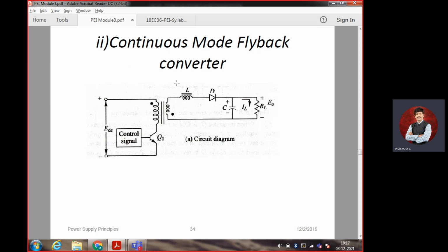So the major advantage here is the inductor. This will store the energy, and this energy will keep on being sent to the load. IL keeps on coming. Previously we depended on the capacitor, but now that we have included the inductor, it will take care of continuous operation. Whatever energy was there is going to continue. Since it is continuing, the separate modes will not be working there. It works continuously.